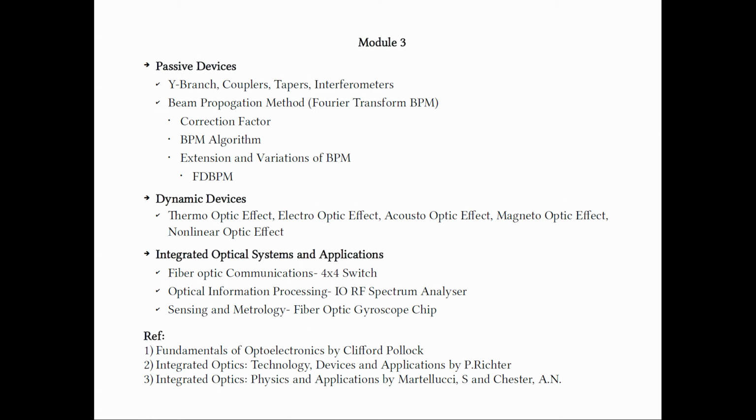So, the electro-optic tensor of lithium niobate has many components, but we can choose the appropriate component by choosing the direction of propagation of the light, the orientation of the crystal, the placement of the electrodes, and so forth. The highest electro-optic effect can be obtained by using the coefficient R33, which has an implication on the amount of voltage that you have to apply to obtain this field. So, if the electro-optic coefficient is more, we can have less voltage to be applied.